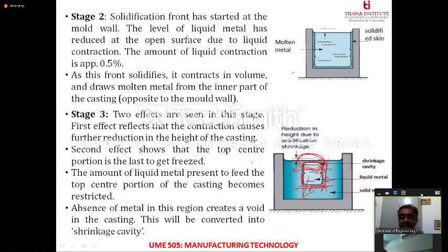As a result, there is efficiently going to be heat transfer going outside the mold. So what happens is, this area that you see over here is going to contract at the end. Now this wall is going to contract like this. As this contraction happens, this area is going to have a void structure, and that void structure is going to cause restriction in the casting, and that restriction or the void structure is going to reflect as a shrinkage cavity over here.